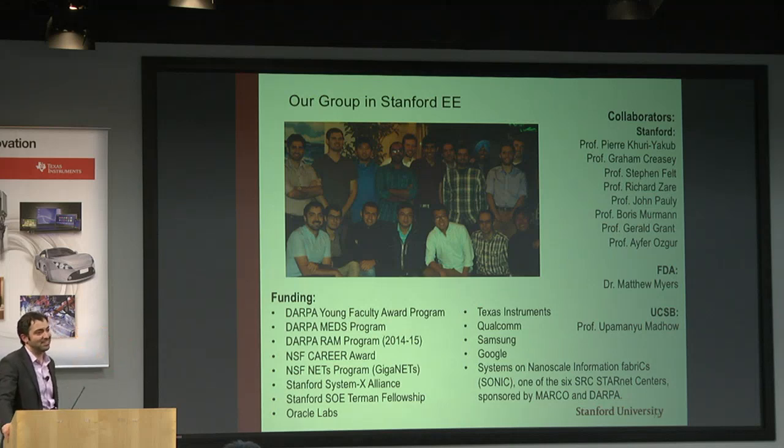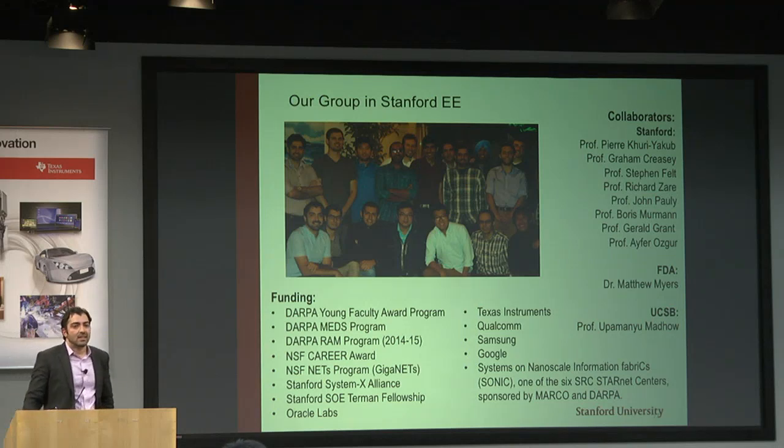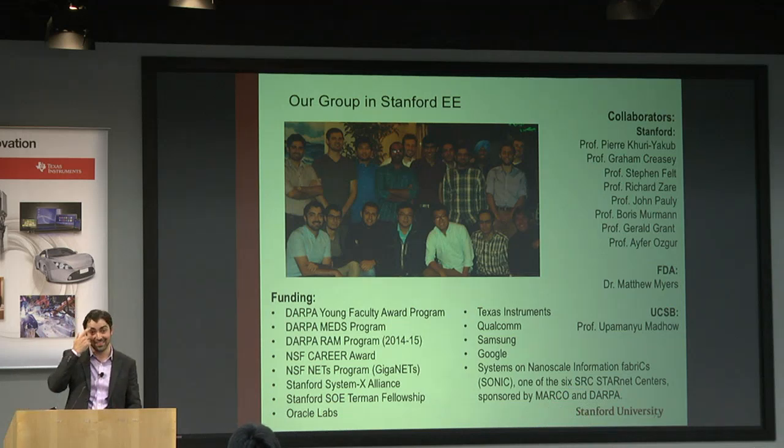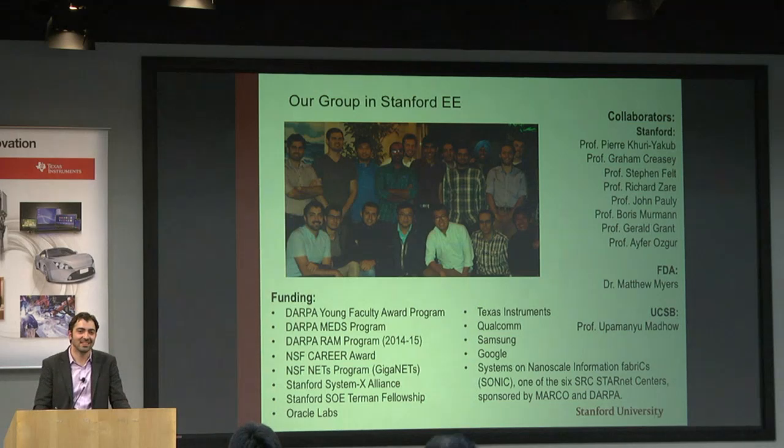Thanks for the talk. I have a question on the assembly part. You mentioned you have the acoustic piece, which is a PZT. How difficult is it to machine this piece and assemble it to an IC, given the non-conventional material that we would have to deal with in the IC process? Is that still a tricky manual lab process, or is there a way to make it easier for batch fabrication, and hence for low cost? Thank you. That's a good question.